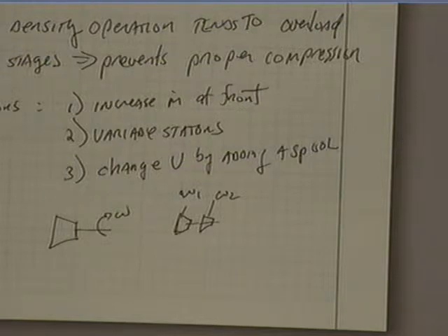Indeed, if you were able to have each stage independently controlled with its RPM, that would probably be the best because you'd be able to just dial it in and you'd have a more efficient compressor. Of course, the problem is that now I've got multiple shafts. It's just not practical to have probably more than three spools.